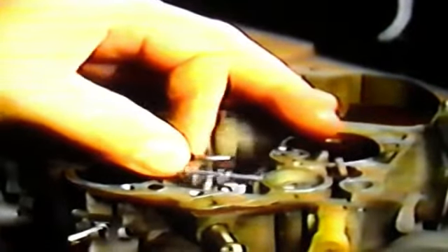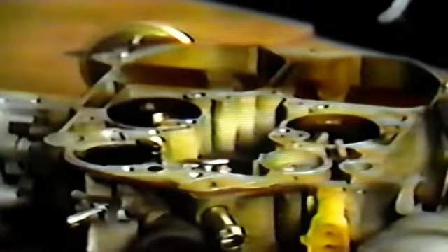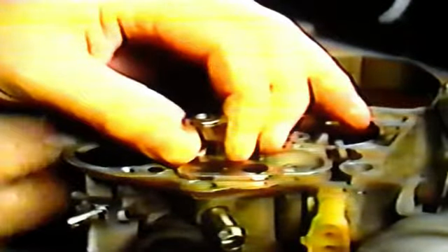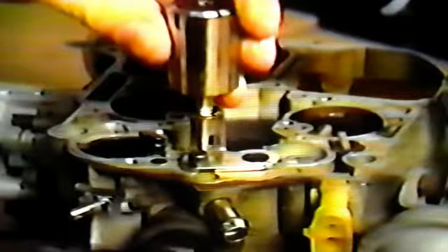Positioning the float is done by applying just the right amount of pressure to the needle seat assembly. It's made up of very soft material, and if you do push too hard, you'll get too high a setting. On the other hand, you don't want to push too soft, or you'll get too low a setting. It's because of this precarious situation that we recommend this special tool. It has a built-in 6-ounce weight to properly position the float, and is the most efficient way yet to assure